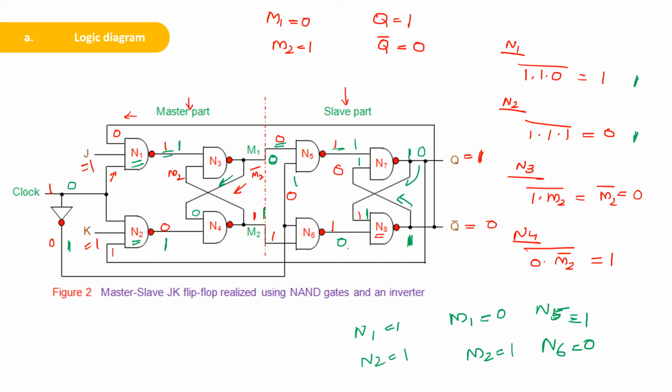So this 0 is getting fed back as the input of N8. Now the inputs of N8 will become 0. Both inputs are 0, so the output will be 1. This is again fed back to N7, and again the N7 output is 0. So this is a stable state. At the stable state you will get N7 as 0 and N8 as 1.